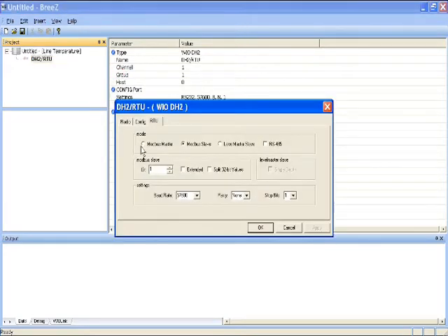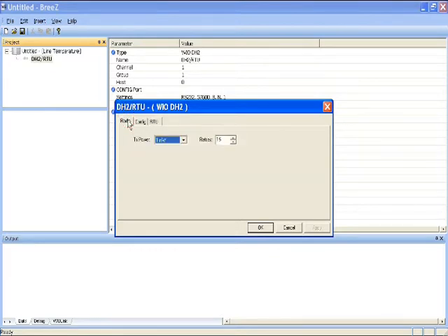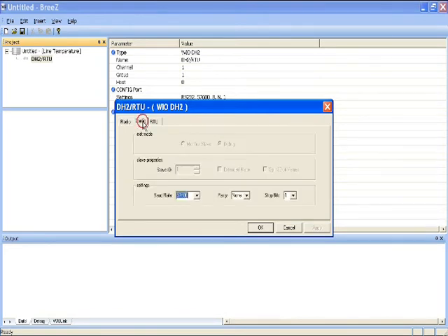Here you will set up all the parameters of the DH2, starting with the Radio tab. Because you have a power supply available here, you are allowed to set up to 1000 milliwatts. 1 or 10 is sufficient for testing. Leave retries at 16. Move to the Configuration tab. The Configuration tab signifies the RJ jack in the back of the DH2, where Breeze comes in with its configuration. It should remain at default 57.6, none, and 1.